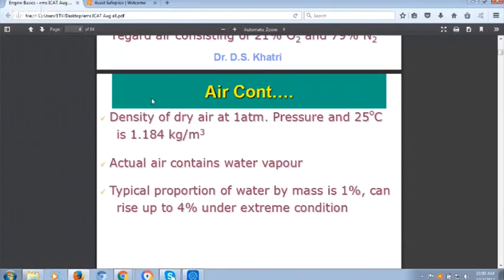And one is in the peak summer noon time, with your same engine operating. So in winter, definitely the engine will take more. Will the engine take more air in winter or in summer? In winter, because the mass of the air will be more. Why will the mass of the air be more? The volume is the same, 150cc. Mass is volume into density, and the density will be more.